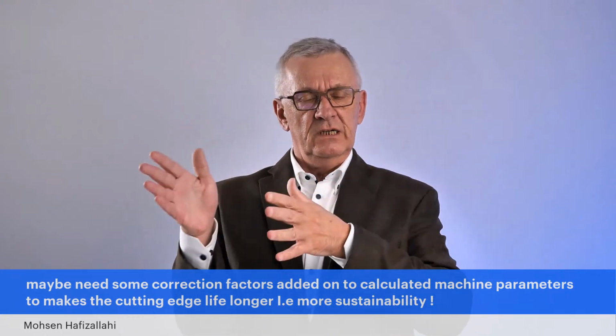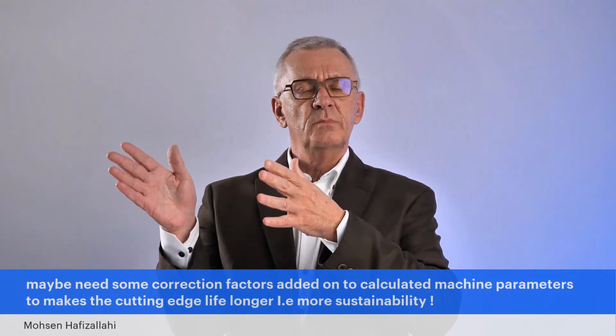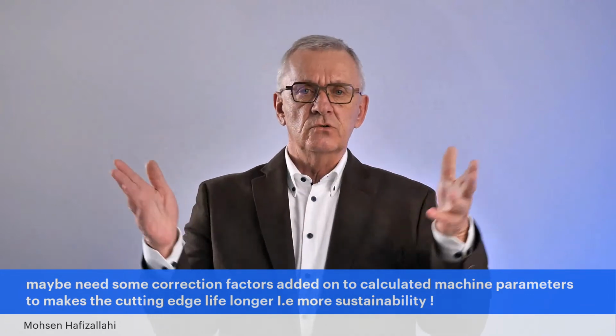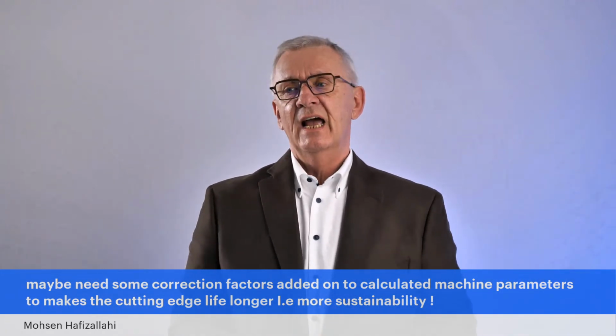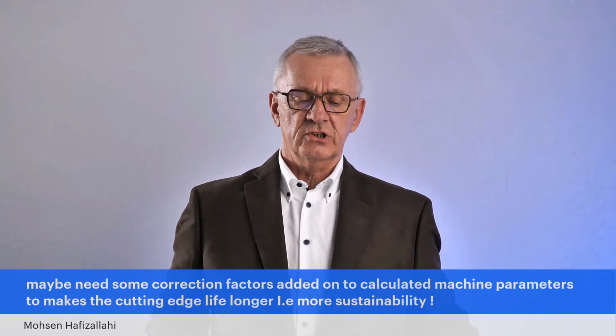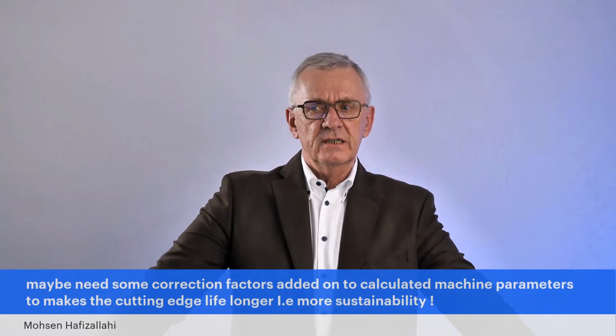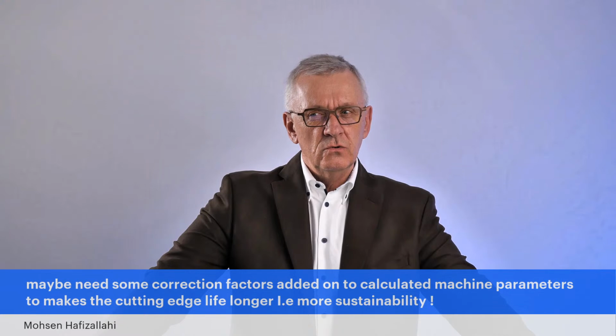And as I said, if you do the test against reality, you'll be confronted with all the little things that you can't take into the big equation. And there we start to work with correction factors. Correction factors in machining is for me a very important thing. Every workshop should know its correction factors, depending on the materials, the machines, the whatever.